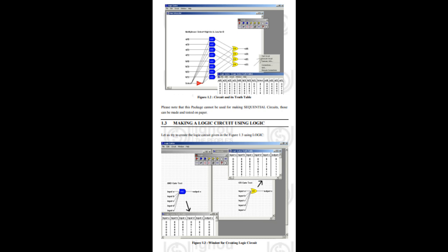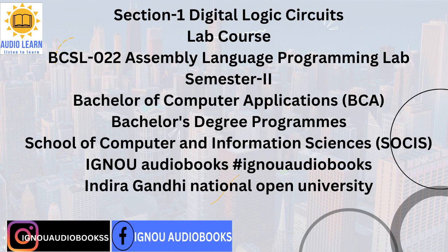Note: 1. You can place as many gates as you like by just selecting AND, then clicking on the screen. 2. To delete any extra gate object, right-click on that object and select Delete from the menu that will get displayed. 3. If you want to change the position of any gate, then first deselect the gate button on the toolbar by clicking on the selected button again. Now click on the desired object whose position you want to change and drag the pointer wherever you want to place it.